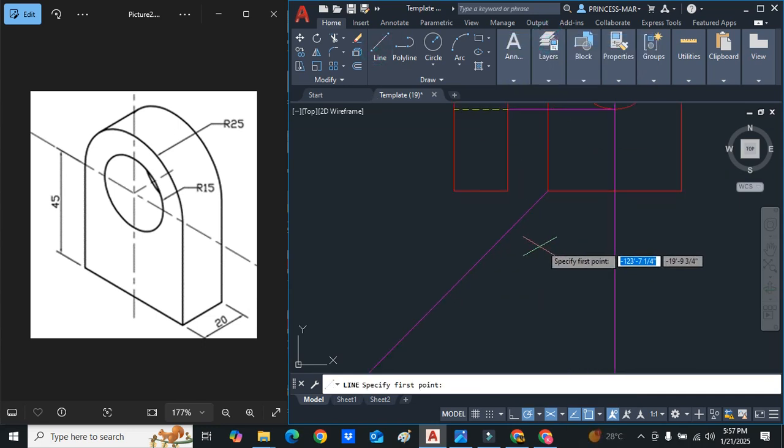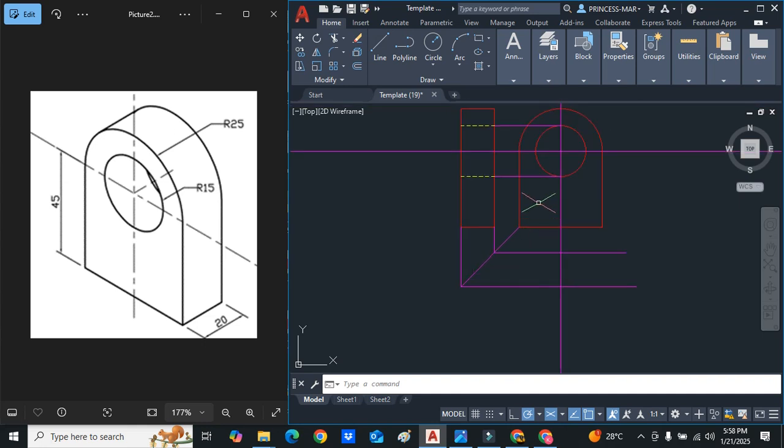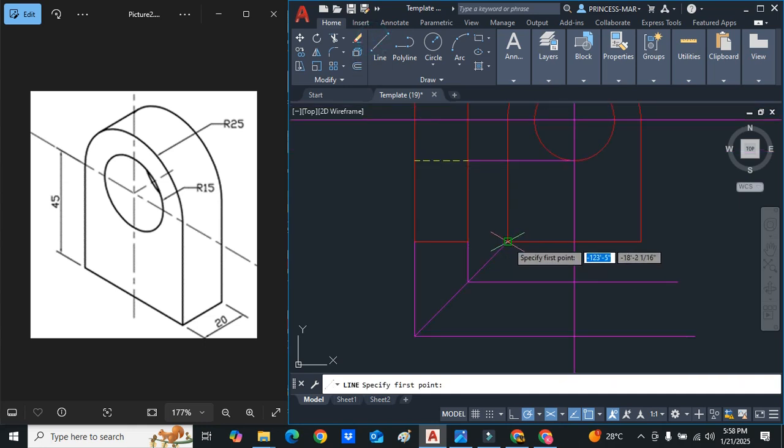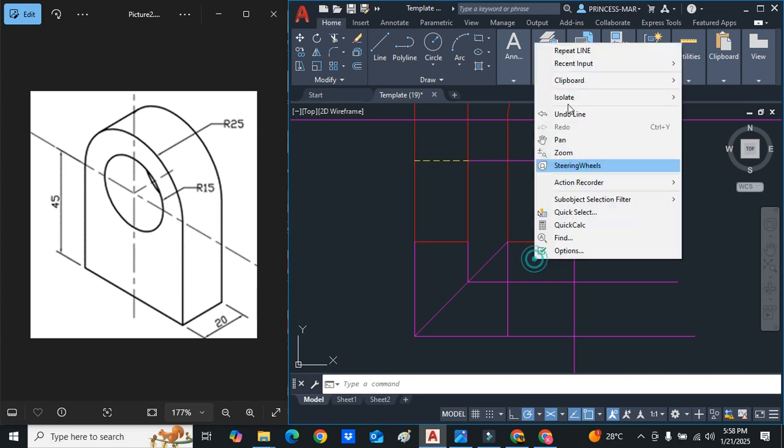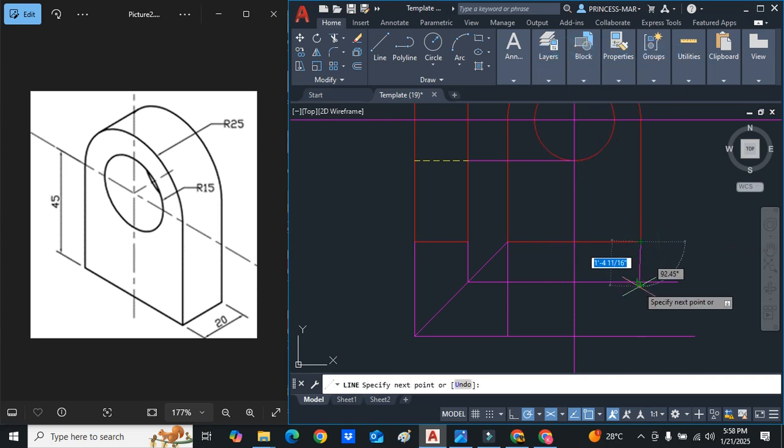Draw the line long, we bring down 1, we bring down 2, and then you're projecting them across. So we have just projected the width of the figure across. Now we just need to project our front view, and that will give us the outer shape of the drawing. So here is our plan view.